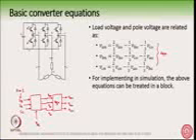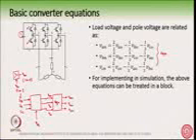So if you put a switch here, the voltage VAO is either 1 or 0 multiplied by the DC bus voltage. This is the DC bus voltage here at the bottom, which corresponds to this VD here.